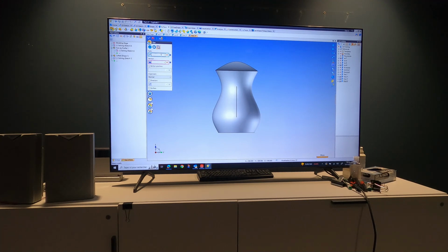You have three options. You see. First one is just the wires, take the first one. Second one is like a tube. And last one is if you use a different profile, like a square or so on. But at the moment it's like a cylinder, so it was the first one. Okay, so the path is this, the sketch you just made, so you can move in 3D to see it's pointed the right way. Yeah, just move in 3D a little.